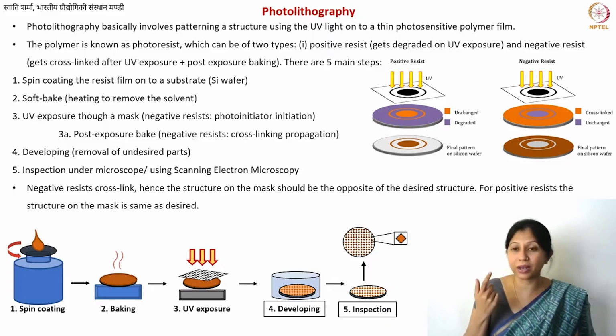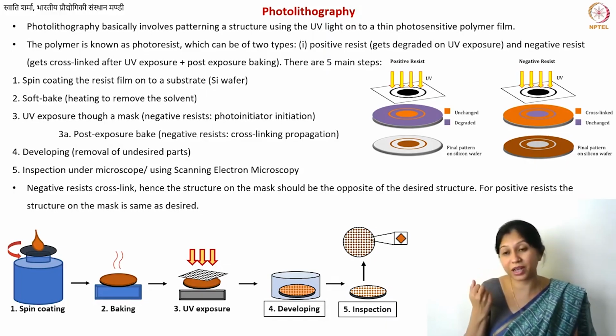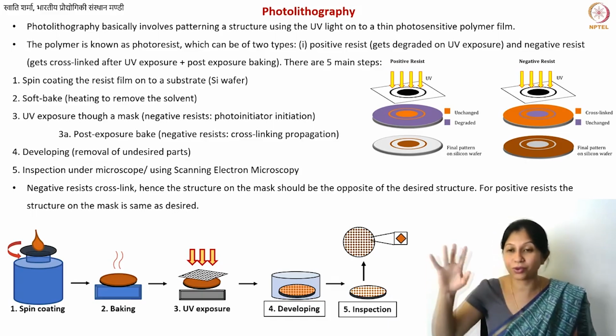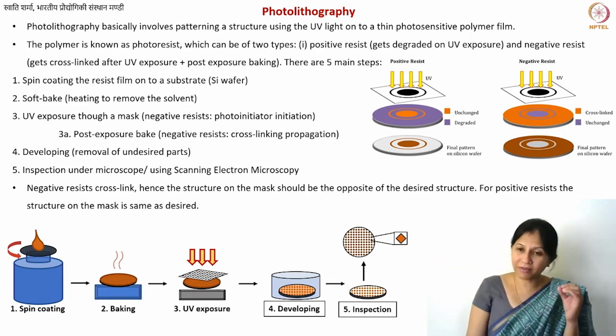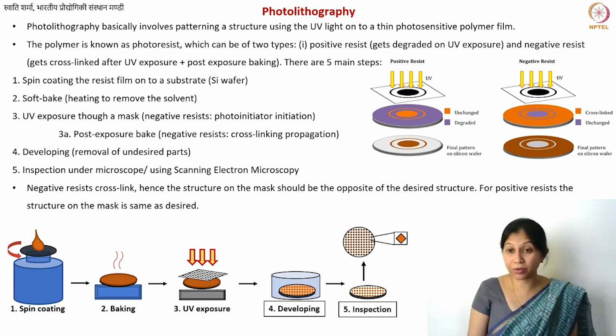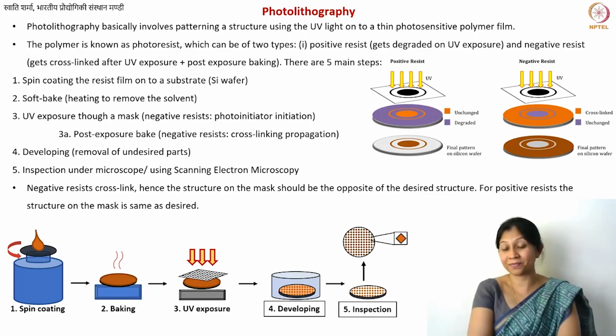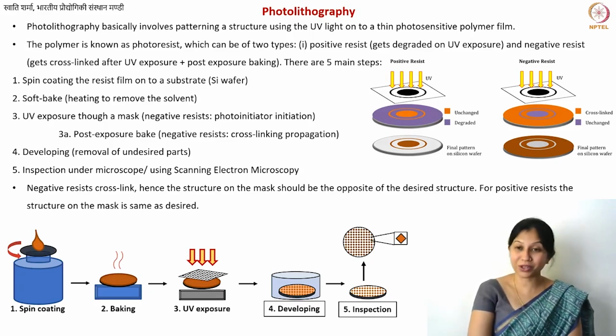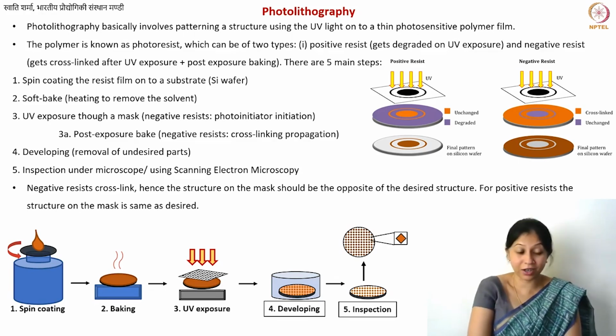Number one, is it worth it? It depends on our application, how high you want to go with electrical conductivity. But even if electrical conductivity was very important to us and heating the device would be better for us, the problem here is that you have a silicon wafer. You need to make sure that your wafer, your substrate, does not melt and does not even get deformed by thermal fatigue. The melting point of silicon is 1410 degrees centigrade.